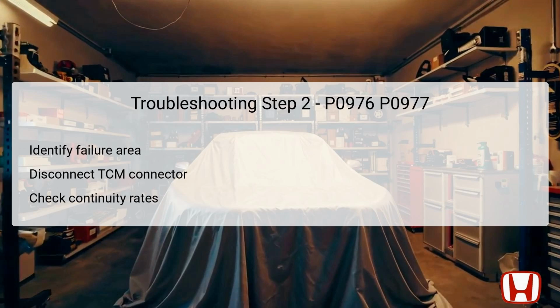While test point 2 is the body ground, a continuity reading of 10.6 to 13.5 ohms is acceptable, indicating that the electrical circuit is functioning correctly. If the resistance falls below 10.6 ohms or exceeds 13.5 ohms, further steps are required to identify the specific electrical fault before proceeding. Step 3 entails verifying the SOLB line for any short circuits that may contribute to the DTCs.